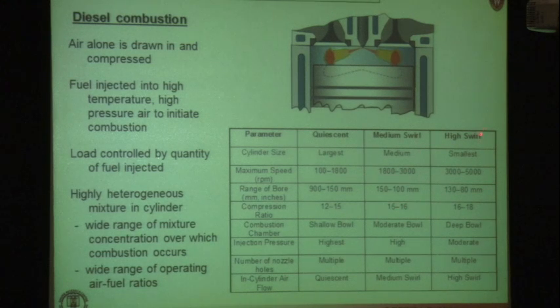And then finally, for the small diesel engines, these are typically characterized with high swirl, relatively low injection pressures, although this is increasing. People are interested in higher injection pressure to enable better mixing and reduce smoke, as we discussed yesterday a little.